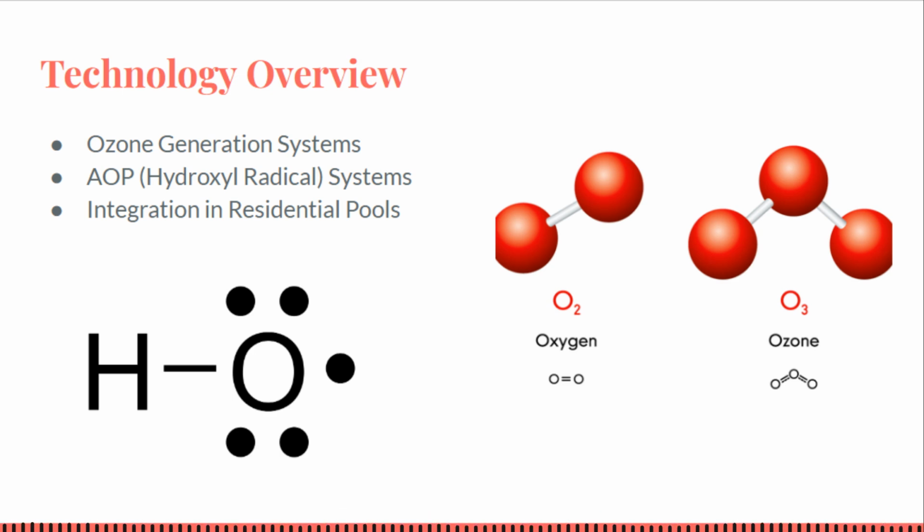AOP hydroxyl radical systems. AOP stands for Advanced Oxidation Process. In pool applications, AOP systems combine ozone with UVC light to produce hydroxyl radicals, OH. When ozone gas and UV light interact, hydroxyl radicals, one of the strongest known oxidizers, are generated almost instantly.